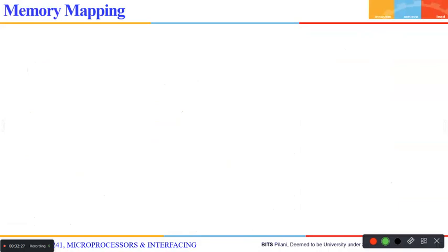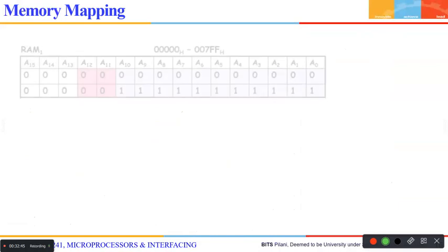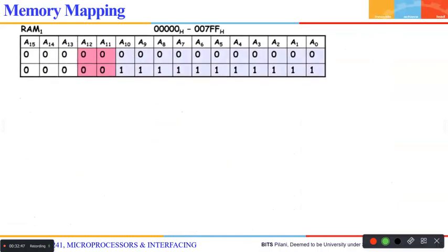So the entire A11 to A19 address lines are distributed among A, B, C, G1, G2A, G2B. How are we going to do that? For that, we need to identify what should be given to ABC and what should be given to the other pins. That will come from this table. See here. What is this table? Tell me. I want you to tell me this.